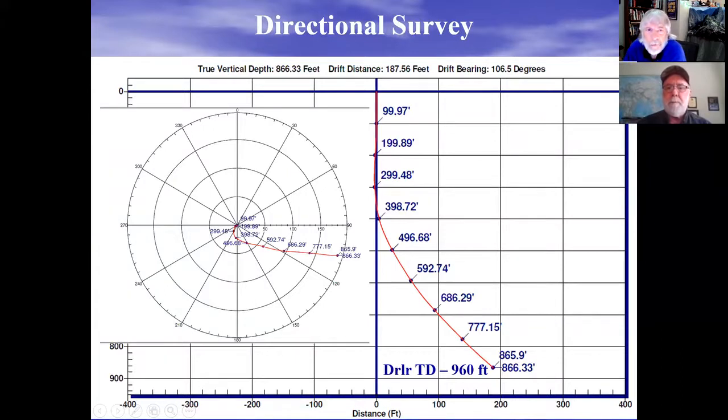And as John mentioned, we really want everybody on every open hole and even cased holes to run the caliper. We also want to see a directional survey on every open hole. This is very important when you're looking to run your casing in the hole and then following that up potentially with running a pipe or your pump down hole. So in this case, from running this directional survey, you can see this hole starting to corkscrew and then really starting to walk out.